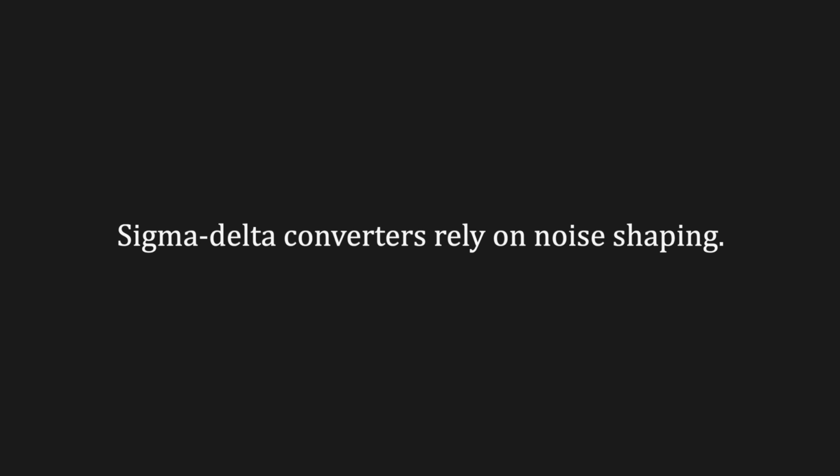Many modern systems use sigma-delta DA converters because they solve several issues found in traditional designs. Sigma-delta converters use extremely high sampling rates, noise shaping, and single or multi-bit conversion. A single-bit system produces a very fast stream of on-off pulses to represent the audio signal, while multi-bit systems generate a pulse-width modulated PWM signal. Because sigma-delta converters have high inherent noise, they rely on noise-shaping algorithms to keep that noise outside the audible range.